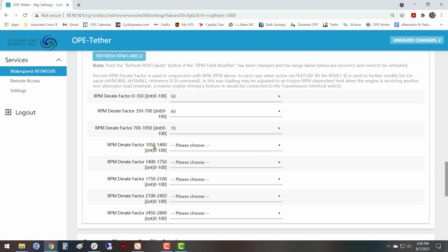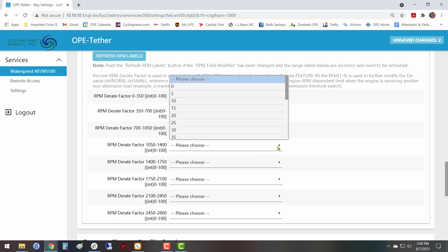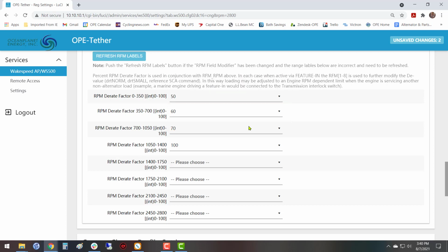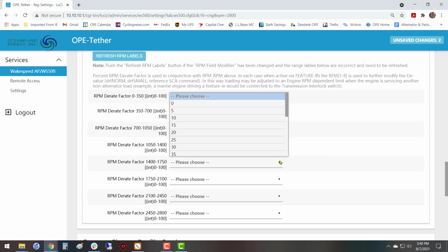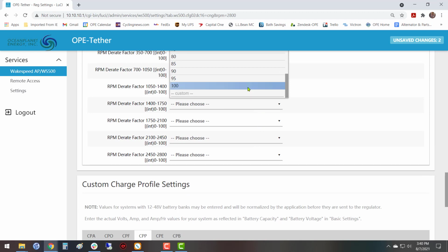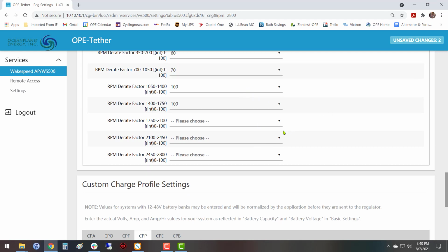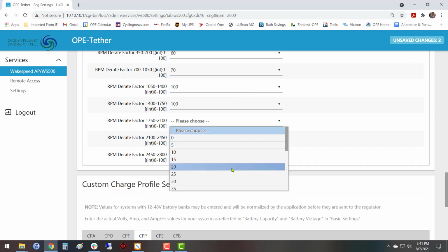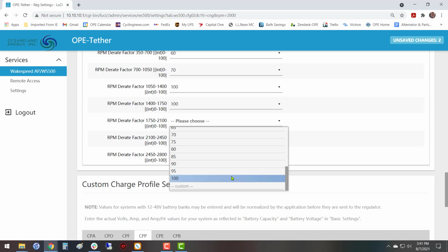And then once we're going about this RPM, the engine typically has a whole lot of what they call headroom or white space available between what's required to load the prop at that RPM and what the engine could actually drive. And all the way up until full RPM, you can pretty much take full charging load.